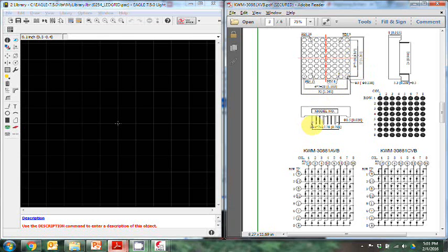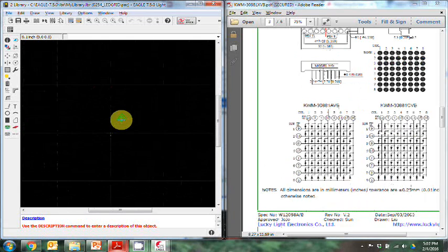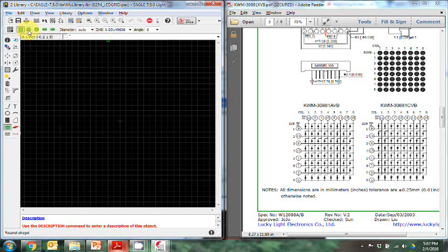And we can see from the diagram that they're spaced about 0.1 inches from each other, which matches the breadboard spacing, and they are laid out about 1.1 inches away from each other in 2 rows. So I'm zooming in way here to make sure that I get down to my basic grid, and I can start putting down pads. I can pick from a bunch of different pad shapes.